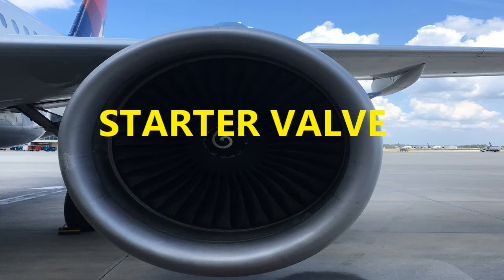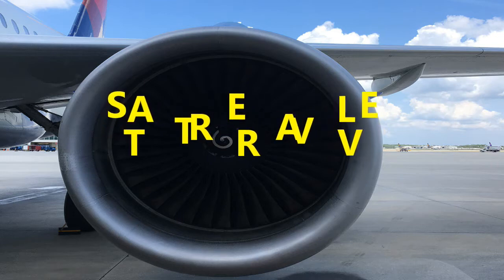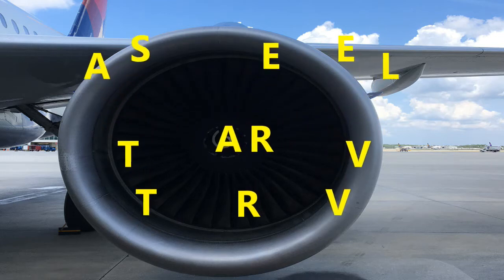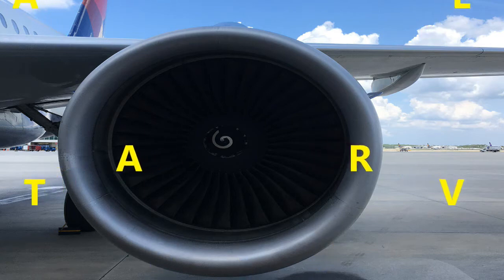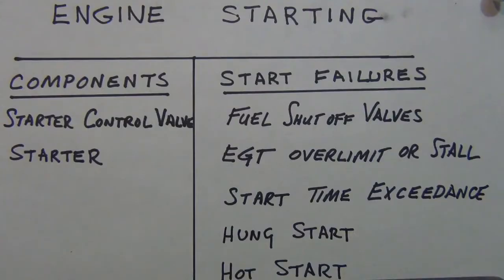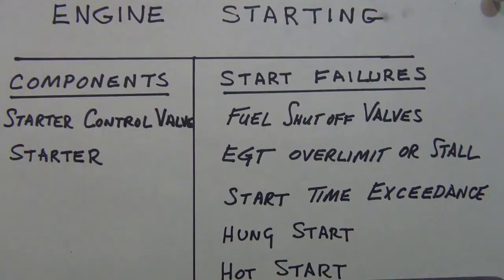On the air starter control valve, just to give you a little description, there are so many different kinds of valve configurations in the engineering or design of it. Here with the control valve, there are 2 major sections: you have your valve body, and you have your air actuator to transmit that energy to the starter. It is electrically controlled by the electronic control unit.